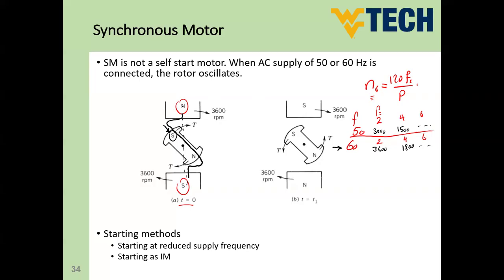So again, the flux lines here try to move the rotor toward this pole. But this is not fast enough because this is a mechanical system. And the supply is going to change very quickly because this is an electrical system, which means this pole will be turned to S, and this S will be turned to N in very few milliseconds.